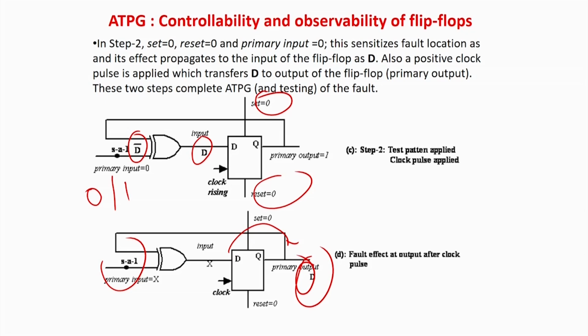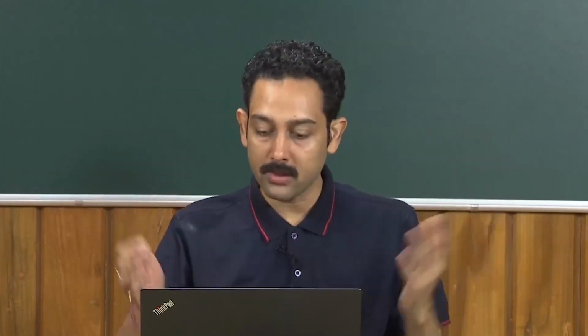How can you directly control a flip flop? By putting a set and a reset line. If you put a set and a reset line, what is going to happen? As I told you, a huge number of extra pinouts will be there, and the story will be a big flop again, and we will be back to square one, which was actually the testing of a combinational circuit in structural mode without any fault, a lot of pinouts. So, this story also came to a catastrophic end.